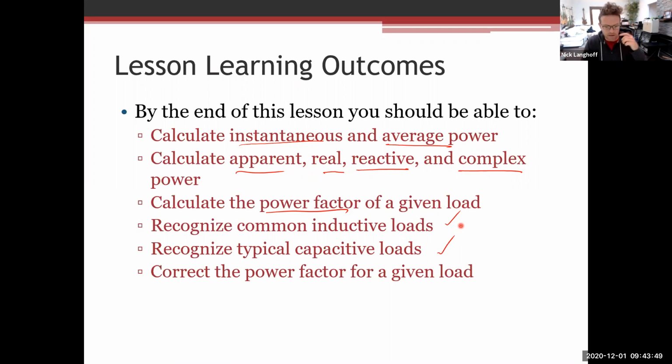We'll utilize a technique that's used in energy efficiency to transfer more real power, that is useful power, as you'll see shortly, to a load by adjusting the load's power factor to match with the circuit. It's similar to the idea of transferring maximum power that we've seen before, where you just match the load resistance with the Thevenin resistance.